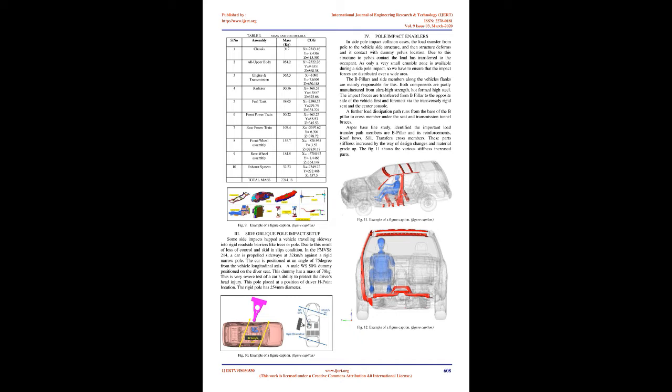LS-Dyna non-linear material modeling. LS-Dyna has a comprehensive material library. The vehicle components are made with many different materials, which should be modeled in the FE model with the appropriate material card. Also the rate of loading should be considered for high impact simulations. A mistake in modeling of material will lead to large changes in the behavior of components. The list of material cards used in the model is shown in Fig 7. Elastoplastic materials are modeled with the MAT24 card, with strain rate dependent stress strain curves.